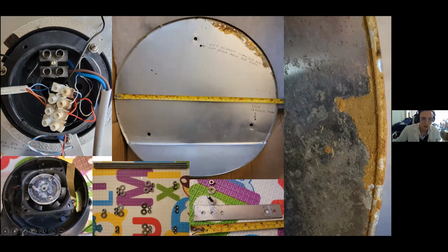These are the other hardware components, the 3 legs, which are stainless steel. The rest of the components are slightly magnetic, so they're a mix of steel and other metals. And he just gave washers and nuts, no lock washers, no lock nuts. So you have to make sure that they're very tight on the frame, or else the spinning of magnets and electromagnetic fields will start to unscrew those nuts.